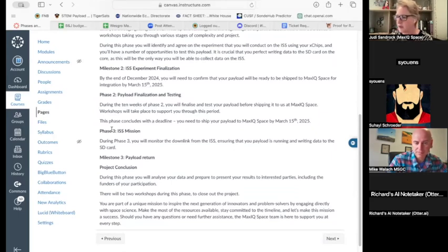One of the groups that participated in the high altitude balloon challenge that we had with NASA in August this year, when they received their SD card back, they found that every time the circuit got powered up, it overwrote the data file. It didn't create a new data file. And with experiments like this, and with the high altitude balloon launches, they get powered up, powered down, powered up, powered down all the time as everyone's doing their different tests in the whole integration process.